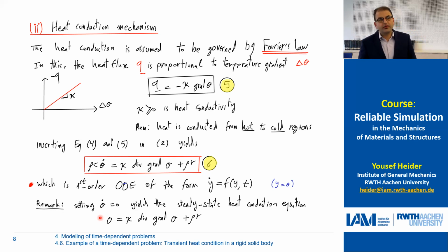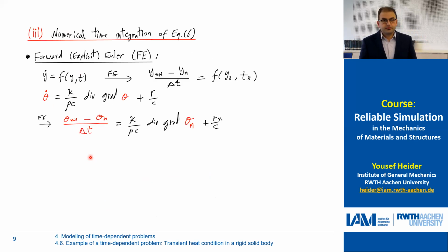It's not a time-dependent computation. But in our case, we have a time-dependent process, and we would like to integrate this equation, which is a first-order differential equation, numerically and in time. So we can use exactly the same methods that we discussed in the previous lecture: the implicit and the explicit schemes, and also the one-step and multi-step schemes.